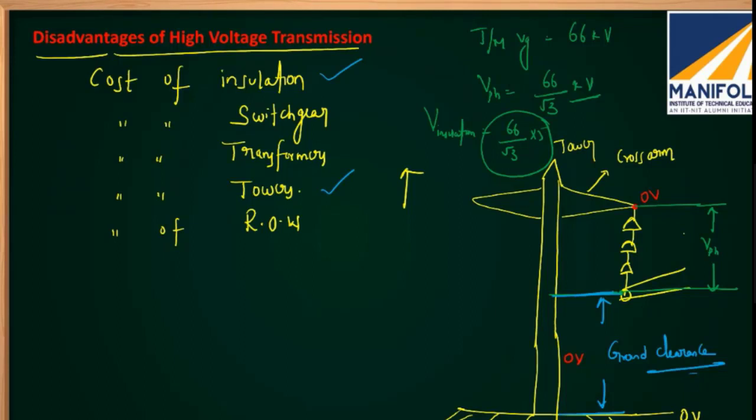So the cost of circuit breakers will drastically increase with the increase of the voltage. For small voltages, you use a single pole MCB to make and break. For 415 volts also you can use a 3 pole MCB, miniature circuit breakers. But when you go for high voltages, say 1000 volts, you require a better circuit breaker because the arc quenching mechanism and the heat dissipation mechanism should be better.